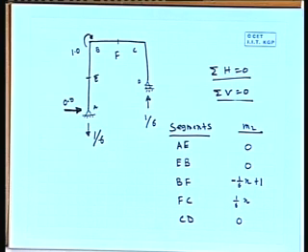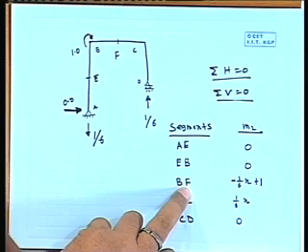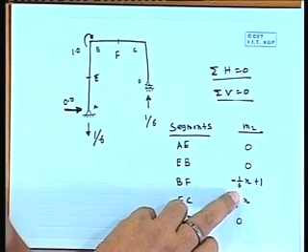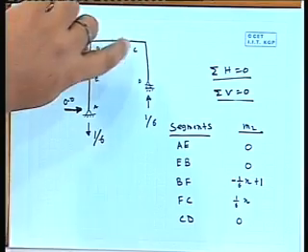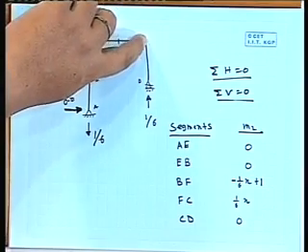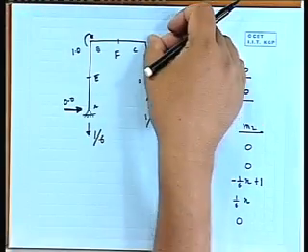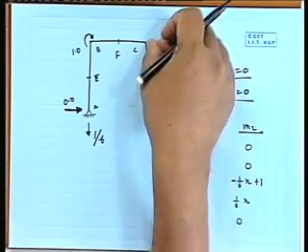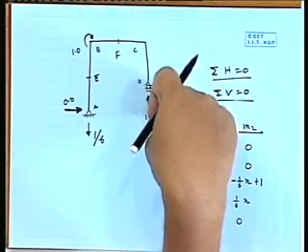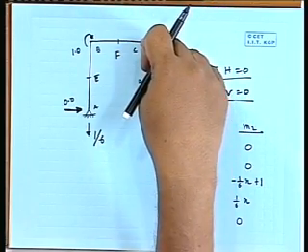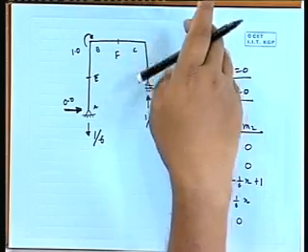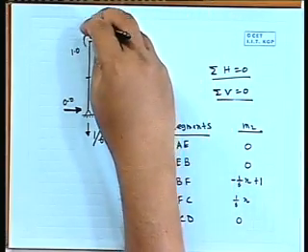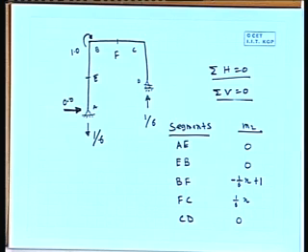Now, we can check something here, say this BF 1 by 6 x into 1, say this end there is no moment, here there is no moment, so it is just axial force. So, say 1 by 6 it will start giving moment, it will vary in a triangular manner and it will go up to there, and this value will be 1 by 6 into 6 will be 1.